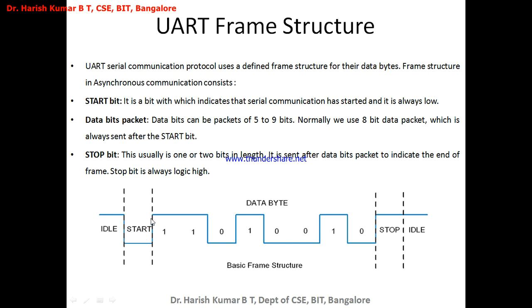Remember, the start bit in UART is always low and the stop bit in UART is always high. The start bit is there just to indicate that the serial communication has started, and it is always low.